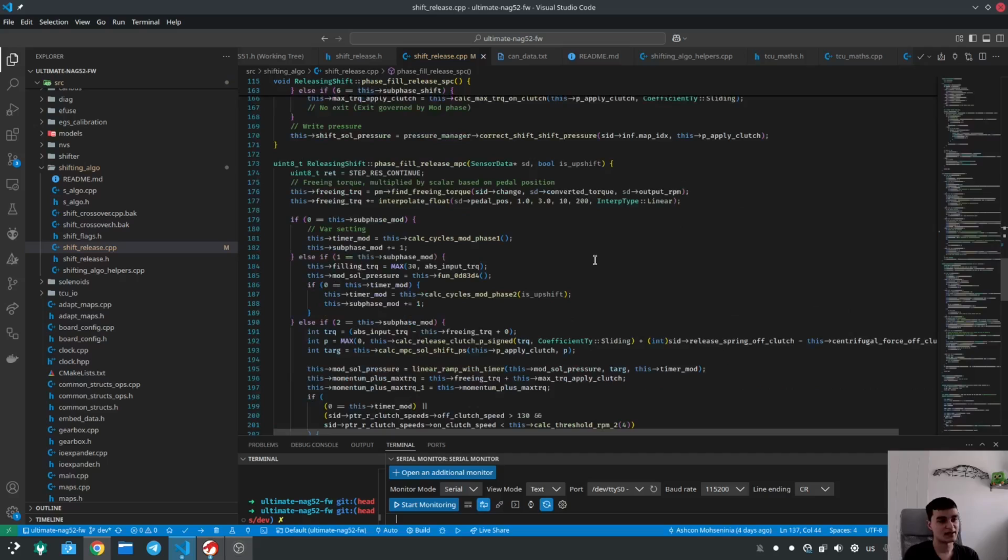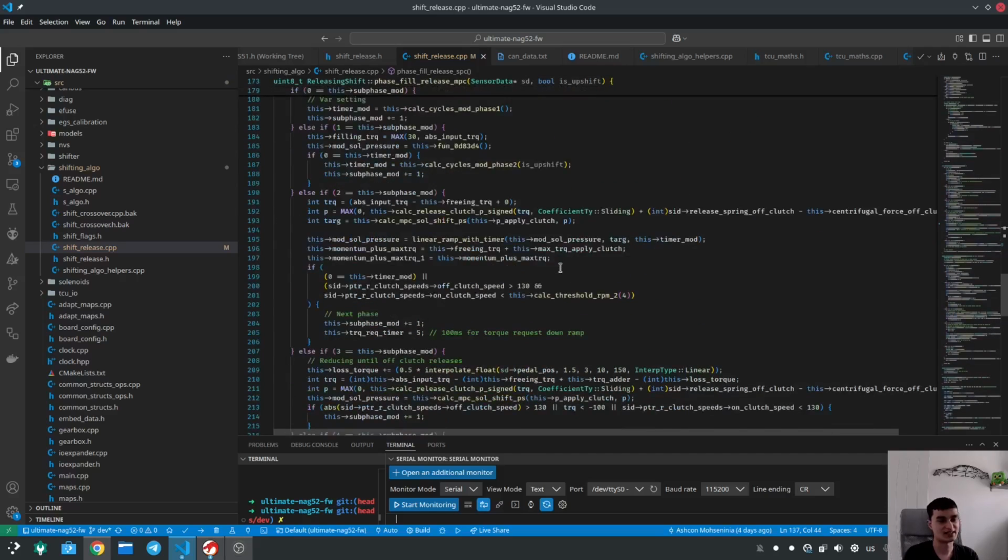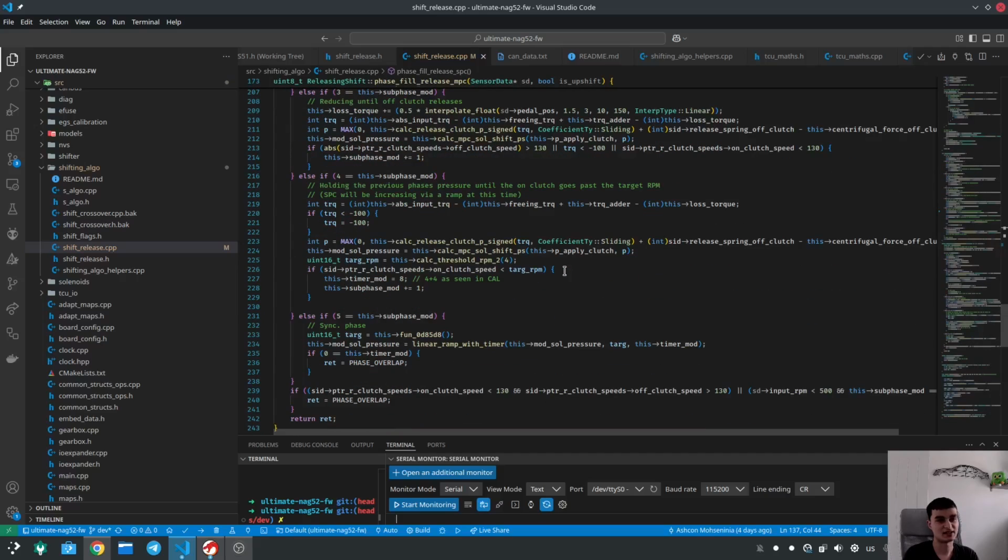But honestly, I've been so busy these past few weeks trying to implement this because it is a lot of work. Only last week I got my car driving with this code because it was so buggy to begin with. What I found is that the disassembly can be quite wrong sometimes, because the C166 has this weird double stack system where you have two stack systems being used at the same time in a function, and because of that, Ghidra sometimes cannot infer which variables you are talking about, and it gets a little confused.